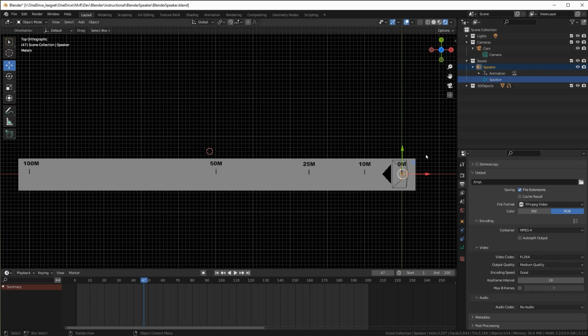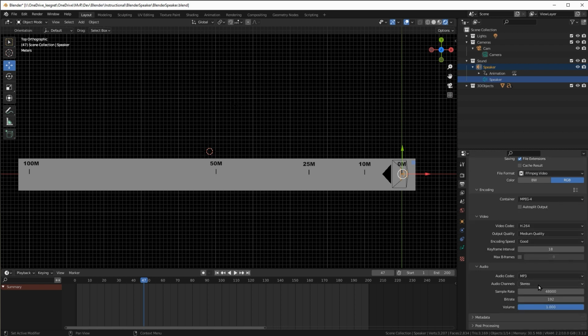So even if you had some audio and it was playing okay in Blender, then you rendered it and went to check your video and played it back and there was no audio in it, chances are it's because of this setting here. So I tend to just stick on MP3 stereo with these defaults and you're fine. Again, you've got another audio setting, you can't go over 1, but you can knock that down a little bit if the balance is a bit off.